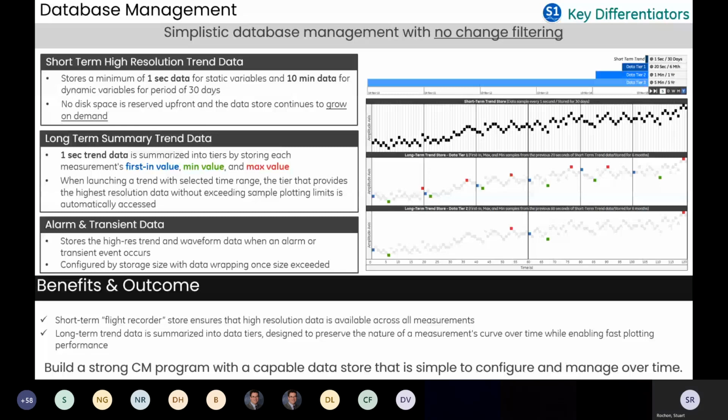So you also had a minimum time between samples and a maximum time between samples. So if it didn't change for, say, 6 hours, it would write another data point just to give you another point on the trend. And if it was changing rapidly, it may have a minimum time between samples of, say, 30 seconds. So it would not write another sample for 30 seconds, no matter how much it changed.